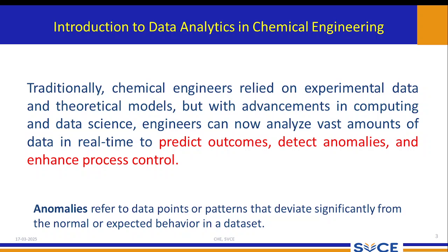So in that case, even at 93 degrees Celsius, at 2000 meters high from sea level, obviously the water will evaporate. Why am I saying this example? When you want to see the relationship between vapor pressure and temperature, either you can go for the Clausius-Clapeyron equation or you can go for the Antoine equation.